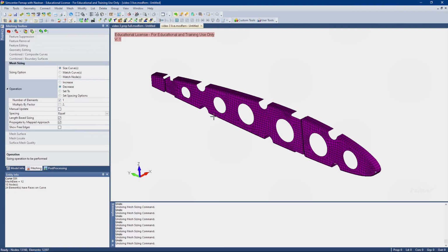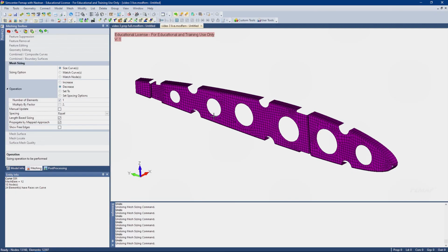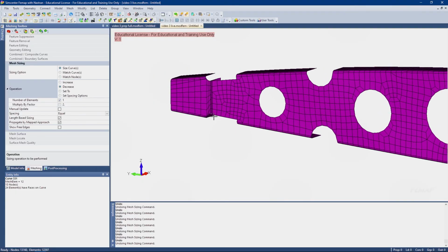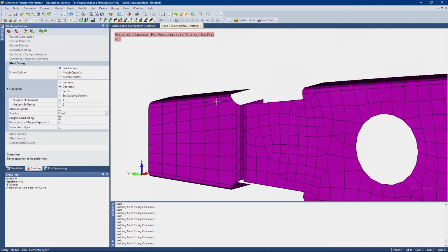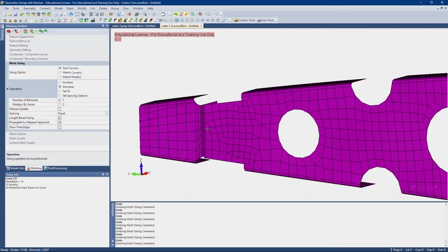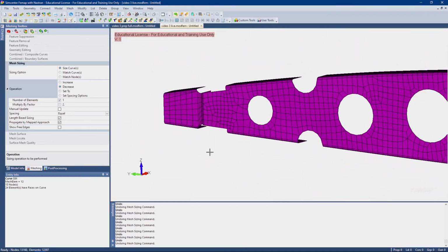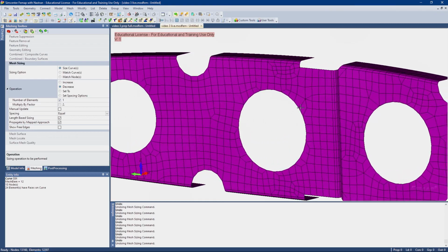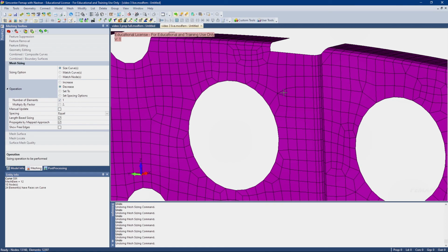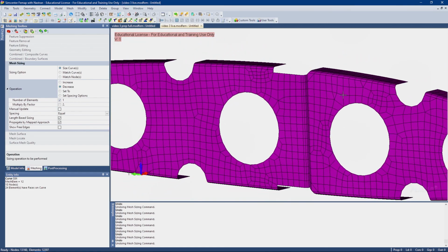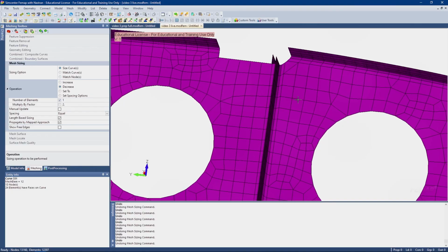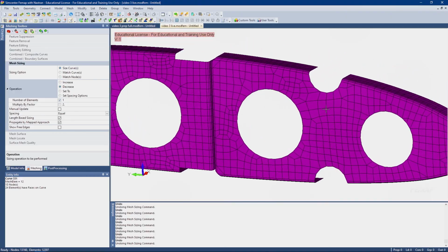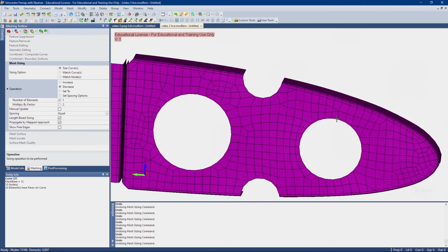There are plenty of places that would be totally fine to pull stresses from. There are just some areas that wouldn't be super great, like back here, this element in this area is not going to be super accurate. There's a triangular element there. There's a few others. Things like this aren't going to be super great, but again, they're not going to be that bad. So I think you'll still be within the right ballpark. Here's another triangular element right here, that might not have the best stress output results, but by and large, it's